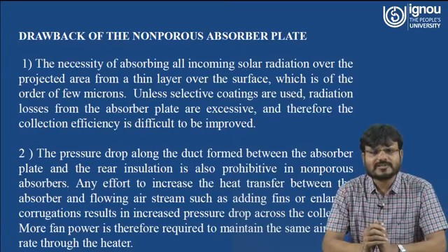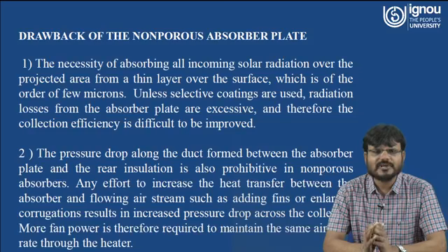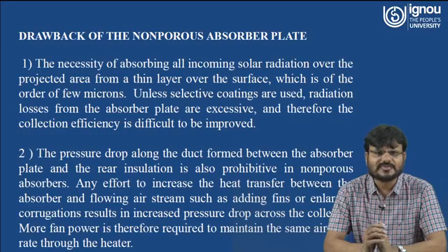Now we have to understand what the drawbacks of the non-porous absorber plate are. First is the necessity of absorbing all incoming solar radiation over the projected area from a thin layer over the surface, which is of the order of a few microns. Unless selective coatings are used, radiation losses from the absorber plate are excessive, and therefore the collection efficiency is difficult to improve. So this is the first drawback.